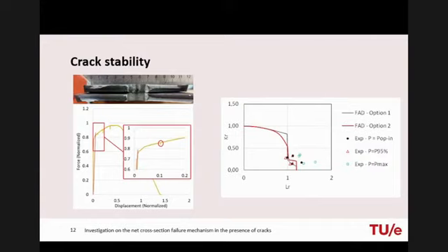We estimate the crack size from the fracture surface. The assessment has been done 3 times with 3 different loads at failure. The first time considered the ultimate load as the failure load. The second one was the peak load where the pop-in behavior starts, which was associated with stable crack extension.